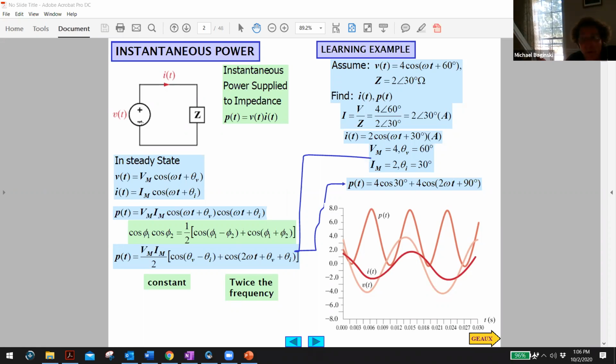This would be negative. You see, it'd be identical in magnitude, opposite in sign. Now listen carefully. That means the sum of all the powers is zero. And that's always true for a circuit. What it's saying is the power supplied is the power dissipated, and that should make intuitive sense to everybody. Do you agree with that?